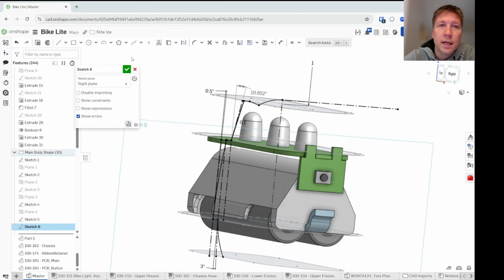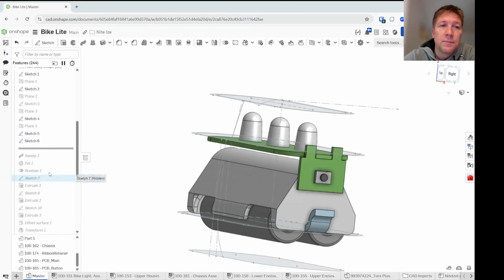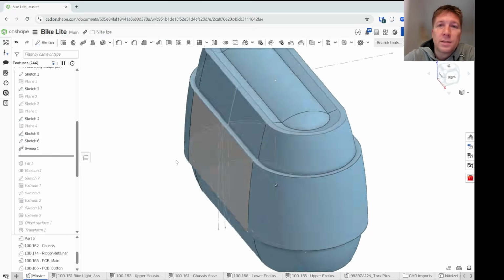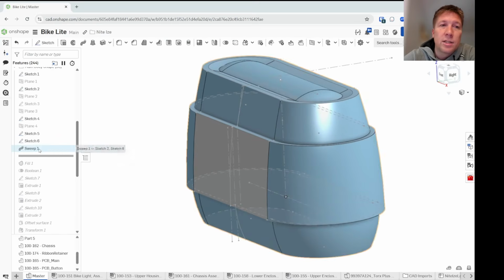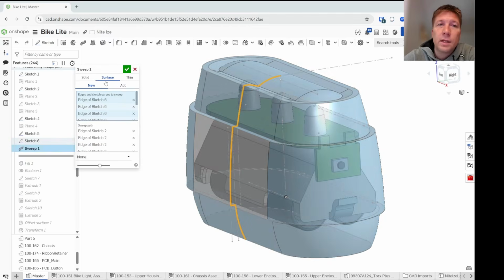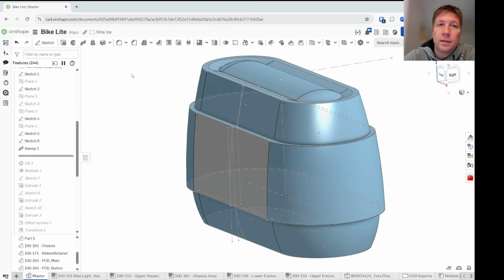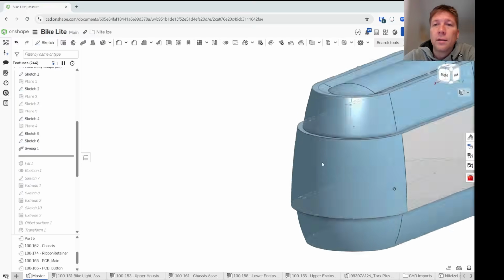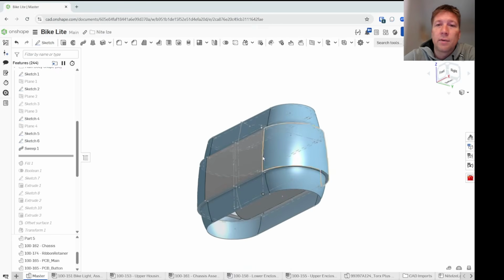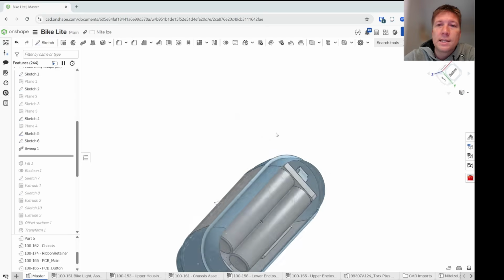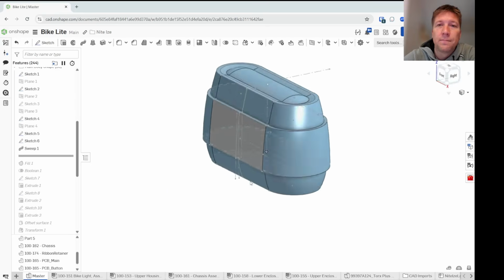And this sketch becomes a surface right here. So what I did is I swept these orange edges along this loop path. There are 4 edges right here that make up that loop. And we now have a surface that basically represents the outside surface of the device.